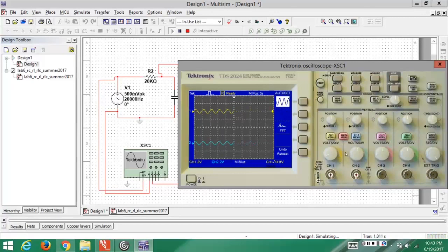What I need to do is compare them and see if they're out of phase and if VR is leading Vs. Remember, from the circuit, channel 1 is connected to the voltage source or the power supply, so that is our Vs, the yellow waveform, and channel 2 is connected to the resistor, which is the blue waveform. So what I'll first do is stop this so that I can analyze the waveform.